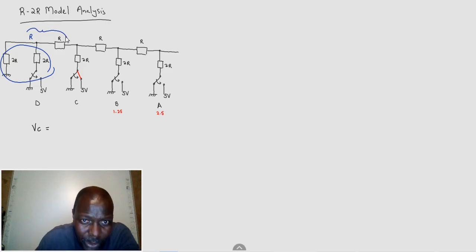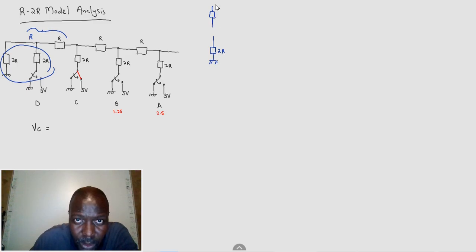It's connected to ground. So what do I have? I've got my one side being 2R and connected to ground. This is when I resolve these ones here, simply by working out the parallel resistance between this pair here. It gives me R, and then you work out the series resistance with those two, and they give you 2R back. But we can't connect it there because this is now our source. So it's not parallel. So this is 5 volts.